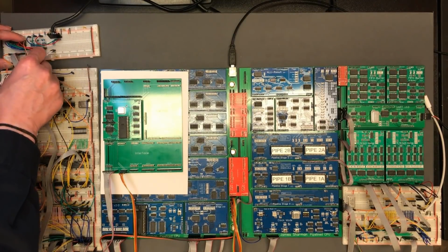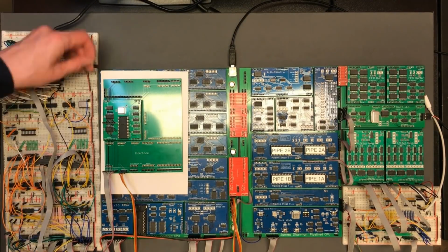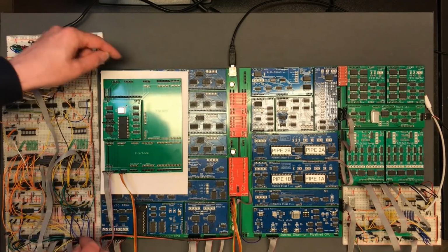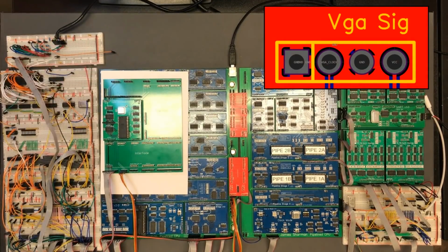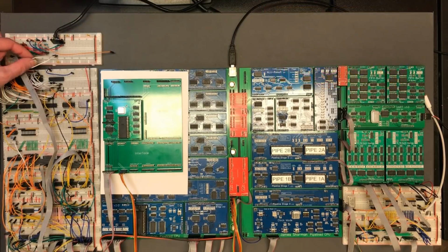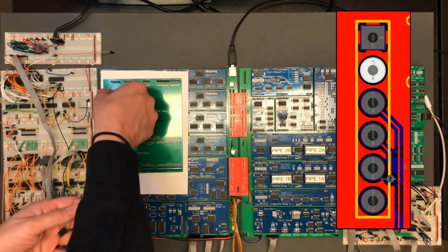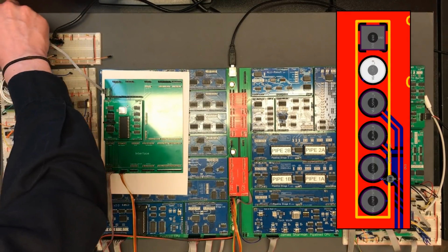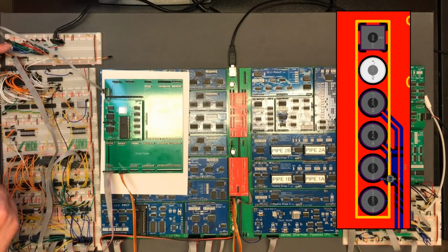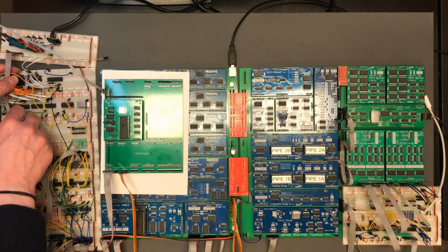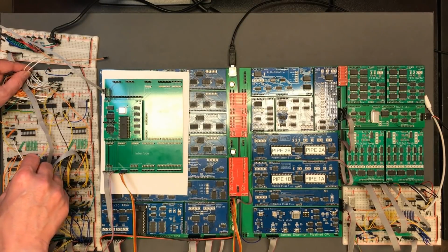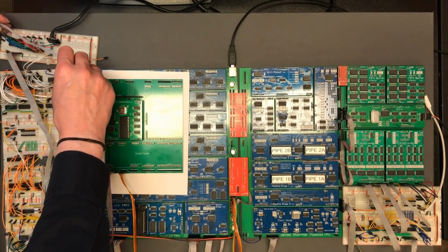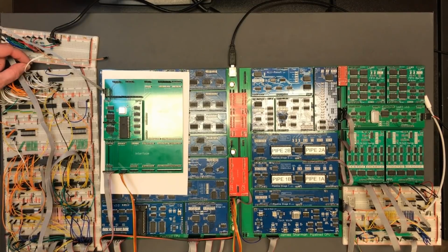Right, so that's a clock line. I can pick that up from the VGA signal when we get there. That's blanking, and that'll be horizontal and vertical sync. Right, so it's blanking connected back. Horizontal and vertical sync. Right, so top pin, that's horizontal sync. Next one across, that's vertical sync. Let's do that first.